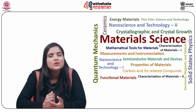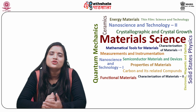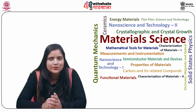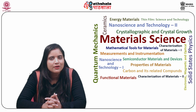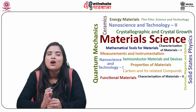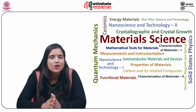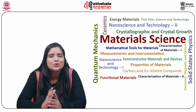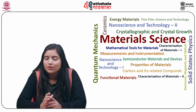Electroless plating is a versatile technique to produce a broad range of coatings. Most popular industrial coatings include low phosphorus, which is hard. This bath is used to deposit coatings having hardness around 60 Rockwell. The additional advantage of this technique is that it provides a uniform all-round coating of complex features.